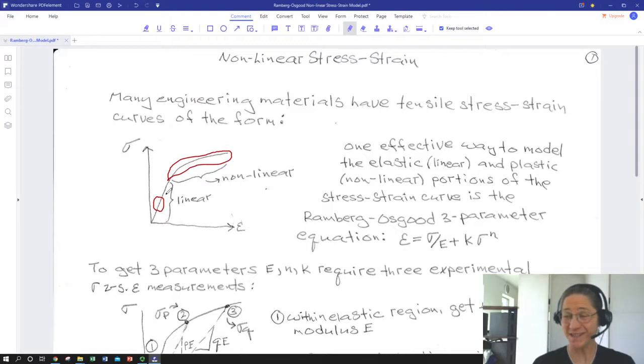It's really easy to model stress-strain behavior in the elastic region. It's linear. It's a line. This is great. If we know the modulus and we know the strain, we know the stress, and vice versa. And we can use our Poisson's ratio and shear modulus and basically deal with any number of loading states, biaxial, triaxial. It's all good.